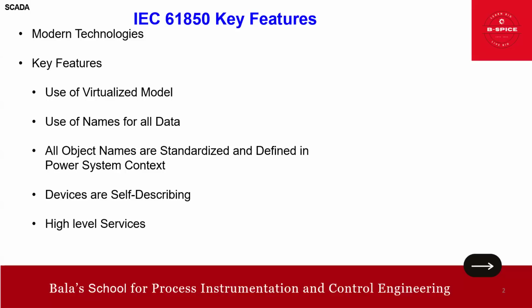Then I also touched upon GSSE. GSSE is nothing but the Generic Substation State Event. It is also a communication protocol defined in IEC 61850, similar to GOOSE, but with some key differences. It is basically designed for exchanging status data using a status list, a list in the sense of a string of bits rather than a data set like GOOSE. So in GOOSE, it's a data set, but here it is a string of bits. And it also helps with the event transfer mechanism.